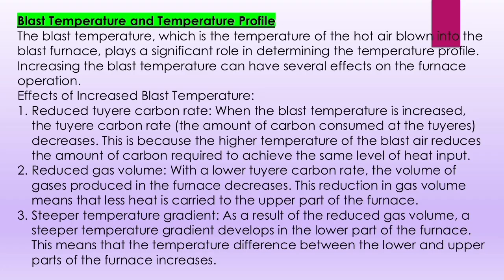1. Reduced tuyere carbon rate. When the blast temperature is increased, the tuyere carbon rate, the amount of carbon consumed at the tuyeres, decreases. This is because the higher temperature of the blast air reduces the amount of carbon required to achieve the same level of heat input.